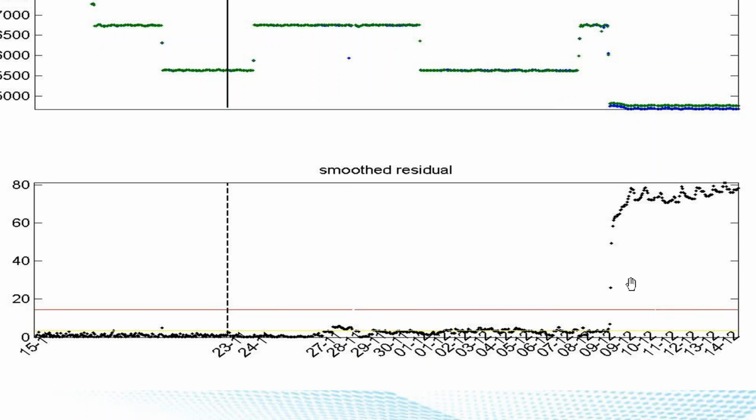So not just leakage detection or safety measures, external factors, we call that. A lot of times people start digging or operating agricultural equipment or even stealing water, and no one knows about it until it's too late. With the help of all the sensors that are installed on the pipeline and the sensitivity of our algorithm, we're able to detect that something is going on externally around the pipe, in the vicinity of 8 feet, with a radius of 8 feet from the pipe.